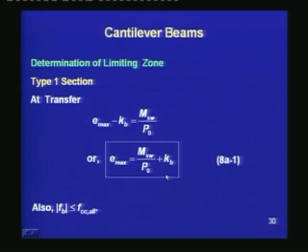Using these expressions, we can calculate the value of Emax at a particular location. Of course, we have to check that the stress at the bottom should be less than the allowable compressive stress at transfer.